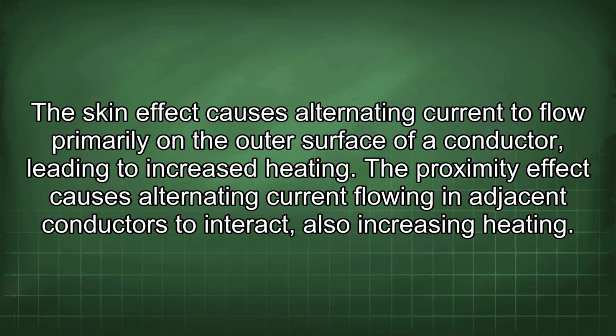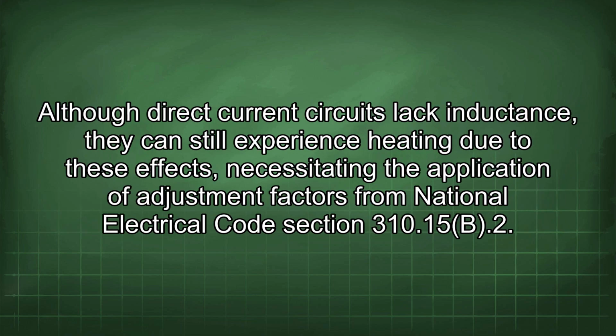The skin effect causes alternating current to flow primarily on the outer surface of a conductor, leading to increased heating. The proximity effect causes alternating current flowing in adjacent conductors to interact, also increasing heating. Although direct current circuits lack inductance, they can still experience heating due to these effects, necessitating the application of adjustment factors from National Electrical Code Section 310.15(B)(2).